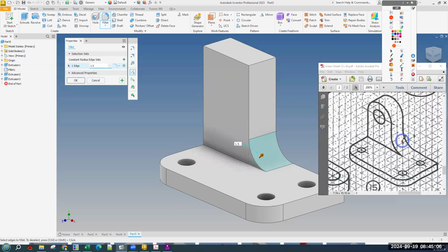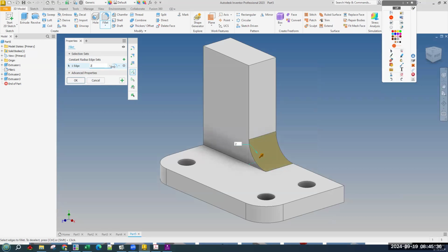You can see these tiny little marks here. These tiny little marks are the center marks for this arc. And the distance from that center mark to the arc is 2. And this one back here is just for the back of it to make the arc. Never mind. So the dimension, which is literally the radius, is 2.